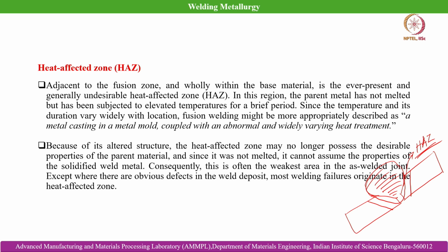So, in this region the parent metal has not melted, but it has been subjected to elevated temperatures for a brief period. Since the temperature and its duration may widely vary with the location, fusion welding might be more appropriately described as a metal casting in a metal mold coupled with an abnormal and widely varying heat treatment. So, please focus on this statement.